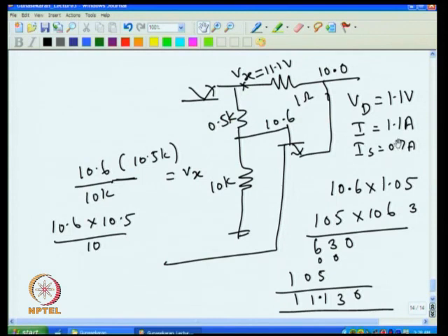If you do that, then one can limit the current at whatever rate that is required. Whatever current that is required for short circuit and whatever is the normal current that is required for normal working. So this is about foldback current limiting. You work out for different resistance, you will get the idea of how to reduce the current under short circuit condition.